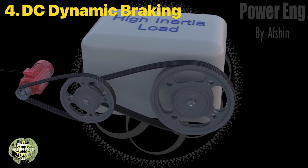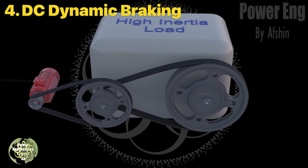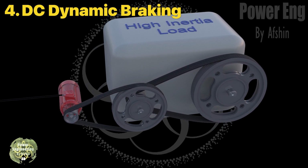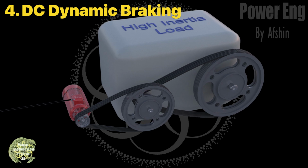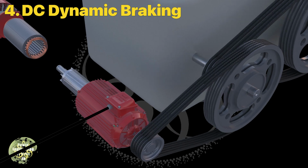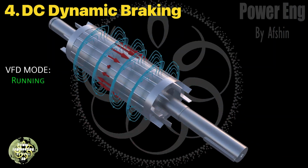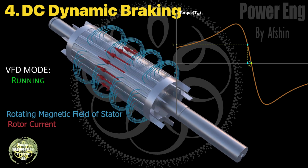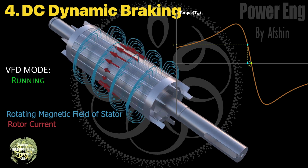This method is suitable for most types of loads and significantly reduces stopping time, including loads such as large piston compressors, large conveyors, high-rise elevators, etc. However, in elevators, braking resistance is also used for other purposes. It's particularly effective for loads with high inertia, allowing them to stop in a short time.